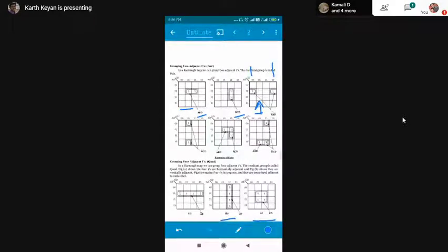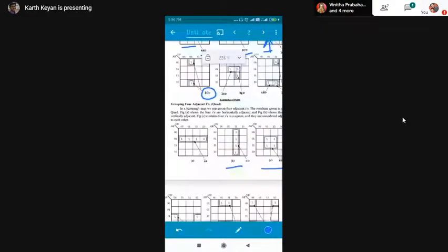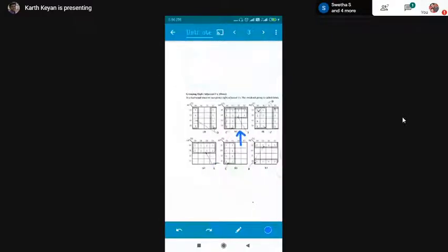So we'll go for the 4 variable map with 16 cells. I have 3 variables after my solution. The number of variables gets reduced as you enlarge your group. If you make a group of 2 cells, you get 3 variables. If it is 4, you get 2 variables. If it is 8 cells, you get only 1.